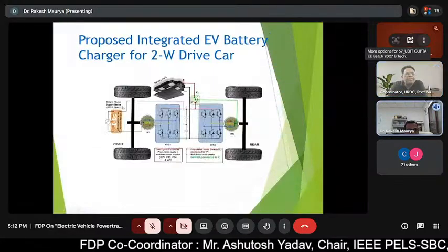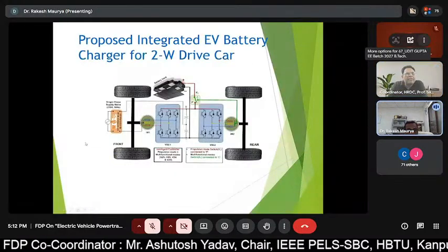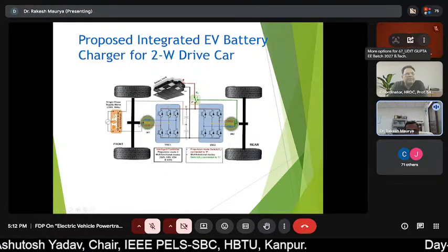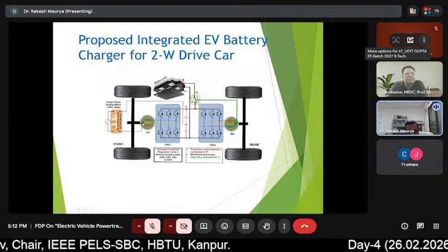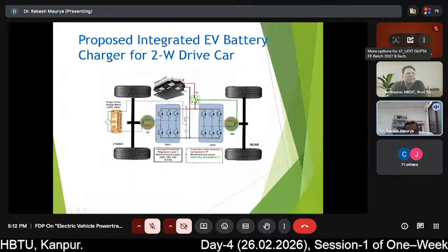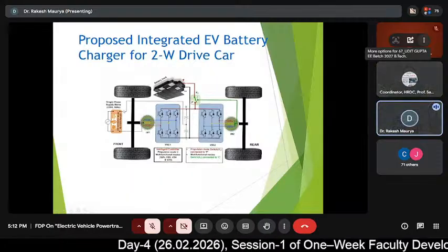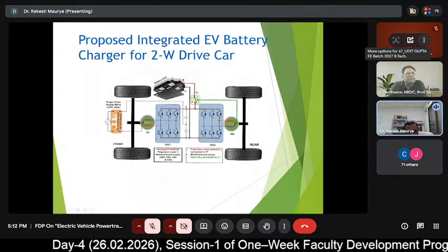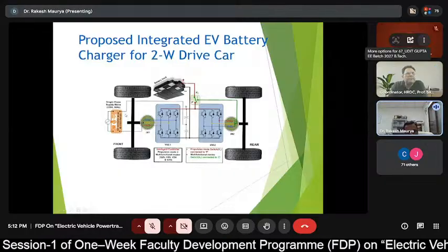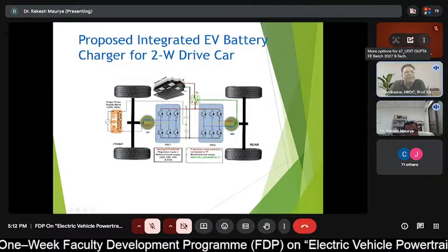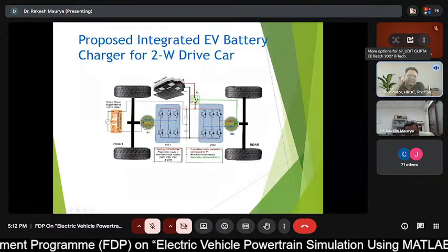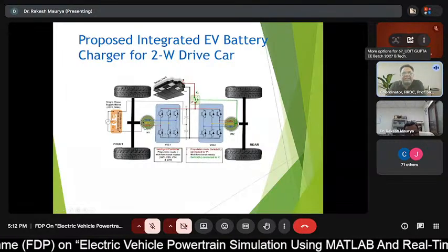No, see here, sir, there is a topology which I would like to explain. This is the VSC, and there is an induction motor. The star point of this is connected to the AC supply, and this midpoint is connected to the AC supply. This AC supply is followed by the autotransformer, the single phase variac, used to, from single phase, make this DC.